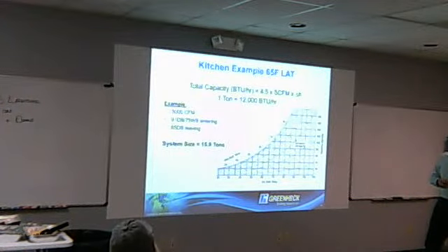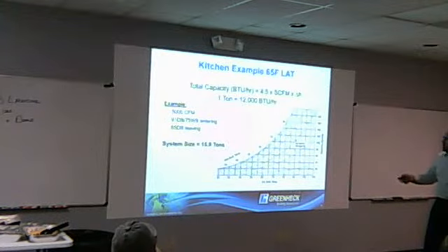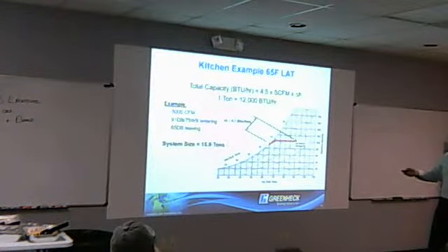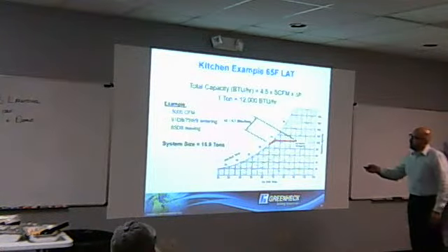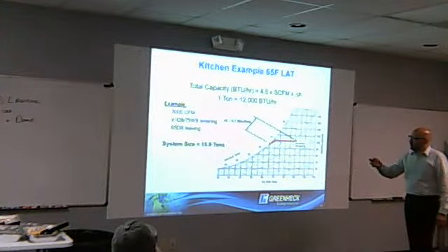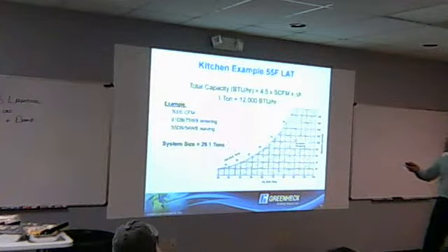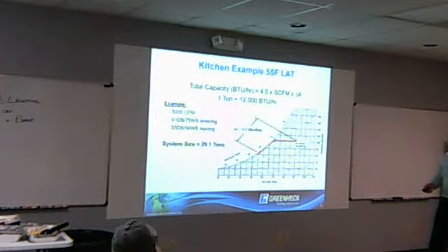This goes through the capacity difference in terms of cooling to 65 versus 55 in a minute. So if we look at the difference in enthalpy, in this particular case, we're talking about 8.5 Btu per pound, which results in just over 15 tons. If we go now to that 55 degree, we go to 15.5 in terms of enthalpy difference, and now we're up to 30 tons.